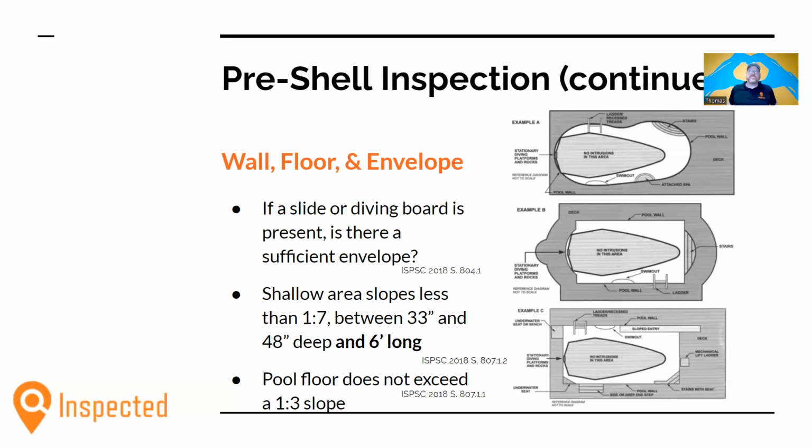This challenge in pool design becomes a little bit more challenging in situations where you have a narrow backyard and the pool is lengthwise and it's a sport depth pool and they've got a beach on one side. That doesn't leave a lot of room for the shallow area to touch the steps and get to that desired 5 foot depth in the middle all at the same time. So be conscious of that when you're discussing with your clients about the pool options and what features are available.